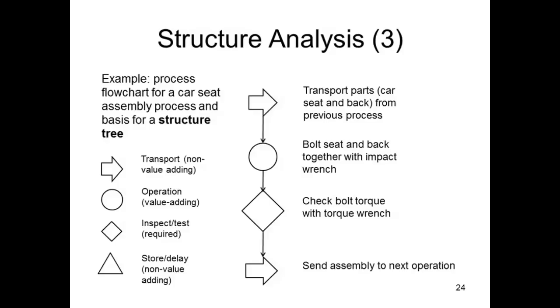The FMEA occurrence ratings echo what Shingo was saying, because what they call behavioral controls or administrative controls don't get a very good occurrence rating when relying on worker vigilance. The principle isn't that workers are careless or don't care or aren't vigilant. The principle is if it's possible to do the job wrong and you do it enough times,